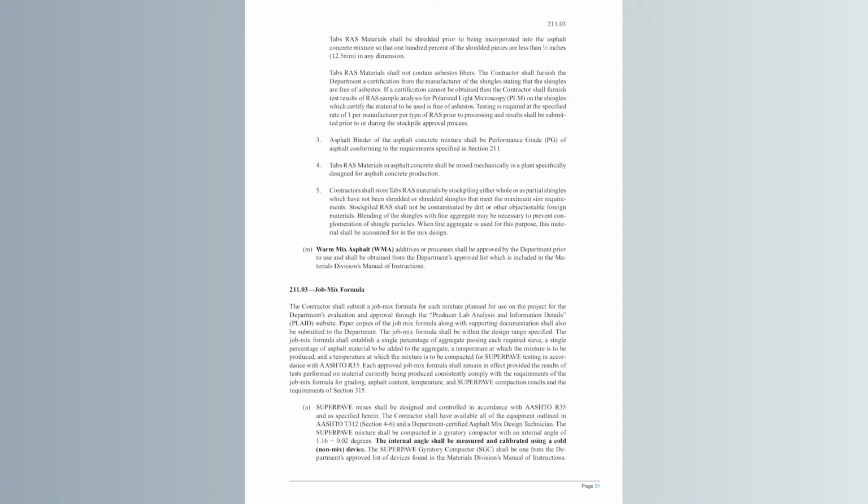Your job mix formula needs to be within the design range of the specification, with a single percentage of aggregate passing every sieve, a single percentage of your asphalt content, a temperature for which your mix is going to be produced, and a temperature at which it's going to be compacted, in accordance with AASHTO R35, as well as what's in section 211.